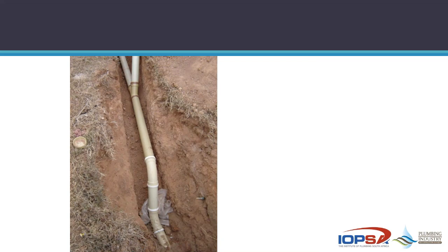Here's an example of a backdrop. If that junction had been repositioned where it's supposed to be and the other end going up for the access, that would have been a spare bend, so that's less material. And by going through 45, 45 and 45, you're doing 3 bends instead of just going down one, or going down the junction and into the bottom one there. So instead of rolling through one, you end up going through 3 here.